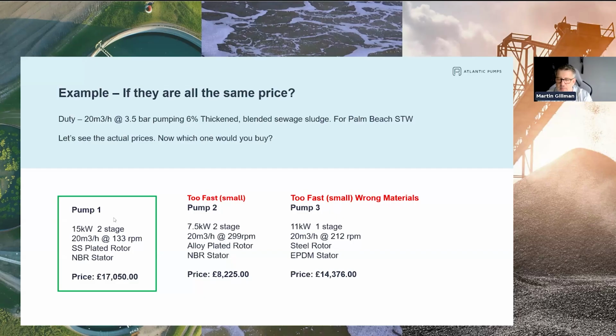I could have this right pump, number 1, but if I put in a standard, just plain steel rotor in that, it would still corrode very, very quickly. Once the surface corrosion begins to take effect on the surface of that rotor, it becomes rough, pitted, abrasive, you know, it will then begin to wear itself away effectively. So again, it's a bigger picture than you think.